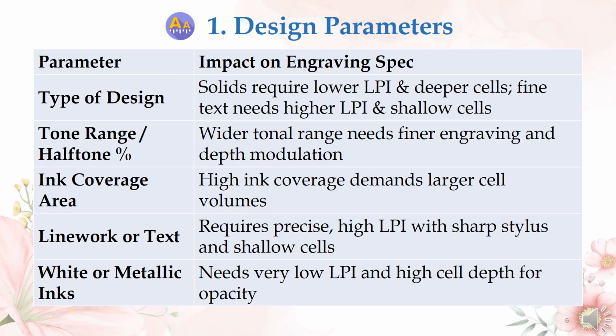Now let's understand design parameters and their impact on engraving specs. Solid areas in design require lower LPI and deeper cells. Fine text needs higher LPI and shallow cells. Wider tonal range needs finer engraving and depth modulation.